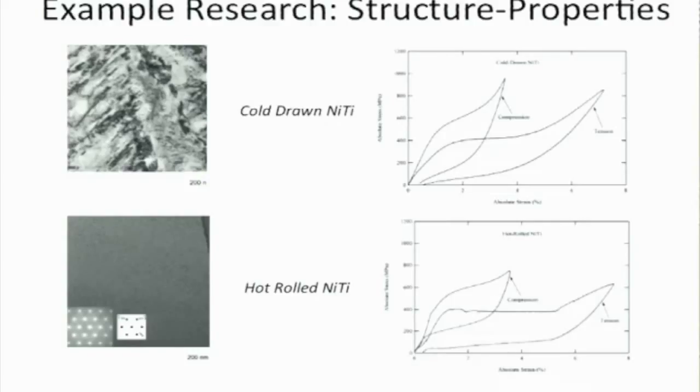And so those who know metallurgy, precipitation hardening is another way to strengthen the metal. When you precipitation harden, you make a fine distribution of second phases, and this provides the hardening. Our concept was, let's just precipitation harden it rather than have this junk in there. And that's what we got on the bottom. We call that the hot roll. That's just a TEM image showing that there's kind of a faint structure, and there's a really nice starry picture in the corner. That's the diffraction pattern. That shows you that we've created a precipitated structure there.